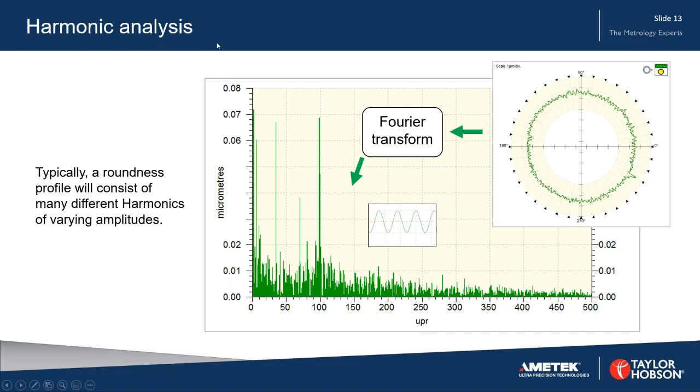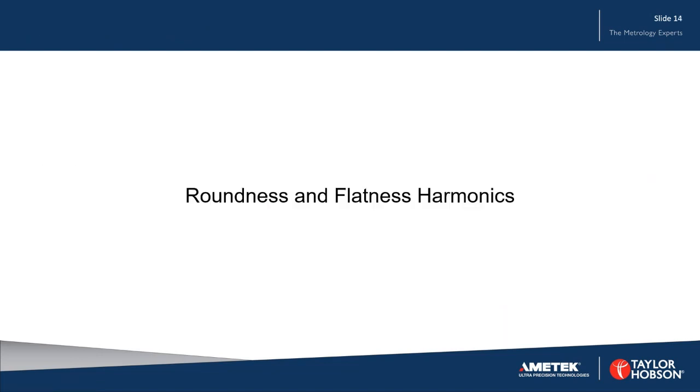So sometimes you'll see harmonic analysis referred to as Fourier analysis. If you look on a drawing, sometimes it won't say harmonic analysis. Sometimes it will just say Fourier analysis. So let's have a look at roundness and flatness harmonics in some real cases.